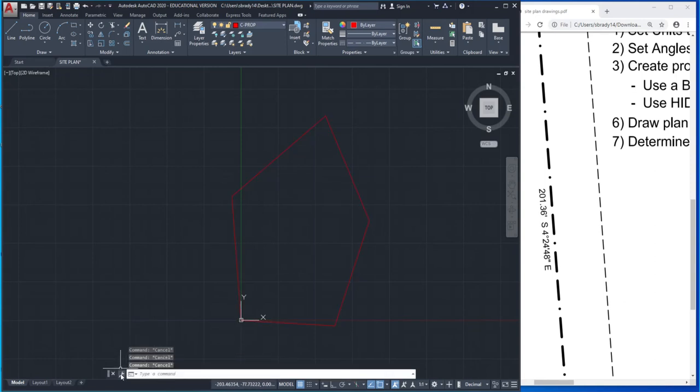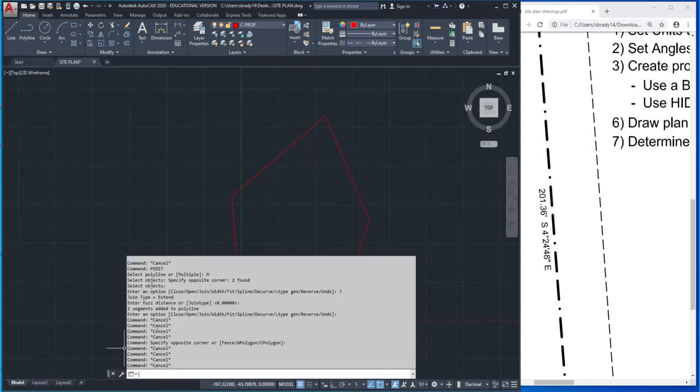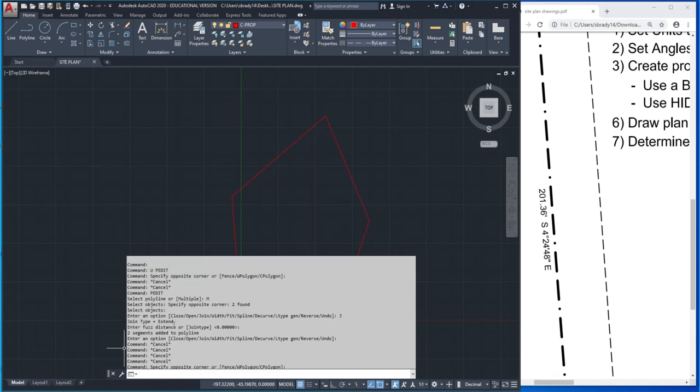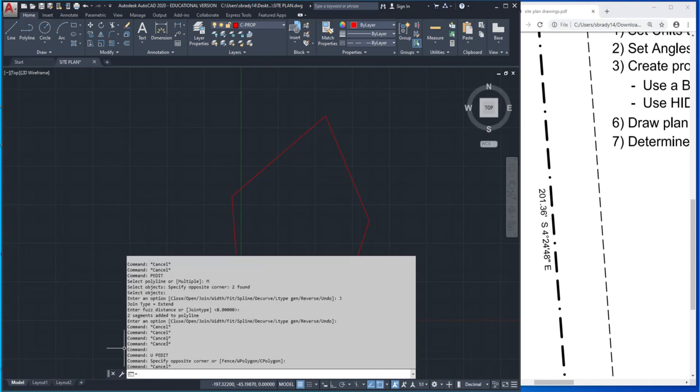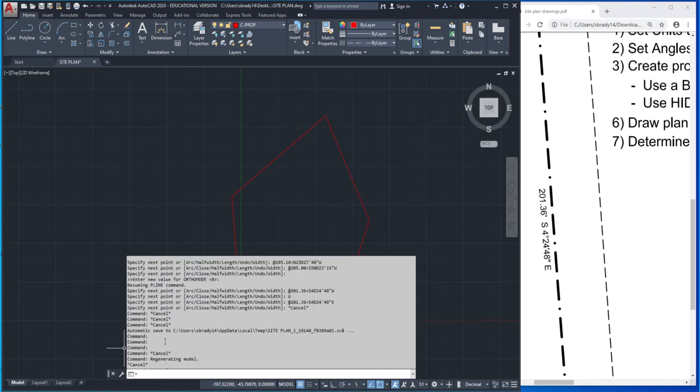You may not have been paying a whole lot of attention to your command line. I want to show you an additional functionality of your command line that will help you. It is F2. F2 is a list function, and it will allow you to see a list of your most recent commands. Sometimes, if I entered that surveyor unit wrong, I'm like, gosh, did I enter it correctly? What's going on? I can browse back and look at what I had done wrong.